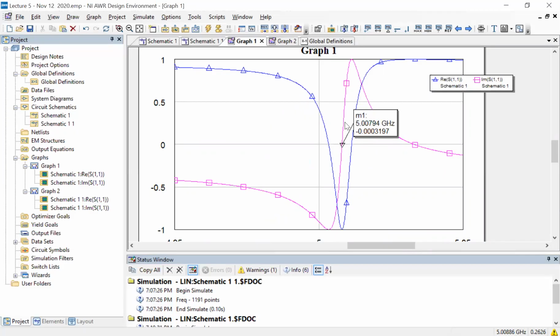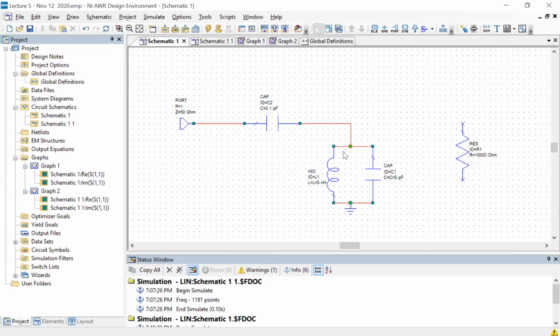So if we draw an equivalent circuit of the full circuit, then an extra capacitance is sitting. That C and R can be transformed in a way so that that C comes in parallel with the LC resonator we have. Exactly. So basically what Supriyo is saying, and this is something I would also add to the homework assignment, is to write this out: this capacitor actually has an effective capacitance which shows up in parallel with this circuit and loads the frequency and pulls it down.